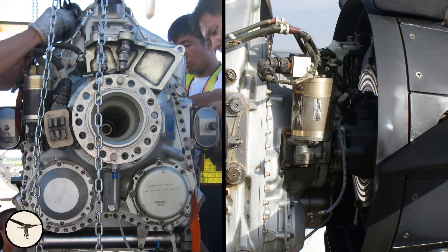The inner part of each propeller blade leading edge has a heating element. The outer part is not heated because the adiabatic heating is sufficient to prevent ice from forming. The heating elements are powered by AC wild, but only when the NP, the propeller speed, is above 63%. This prevents damage when the propeller is not turning. The electrical current is transferred via brushes on the propeller gearbox to metal rings on the propeller spinner bulkhead.